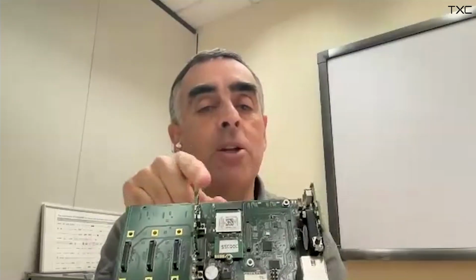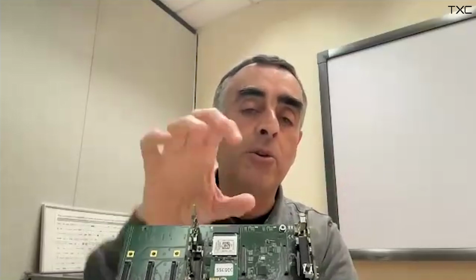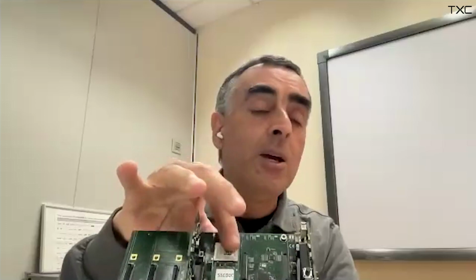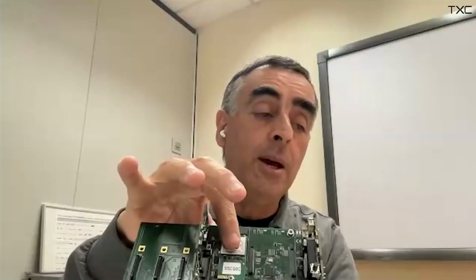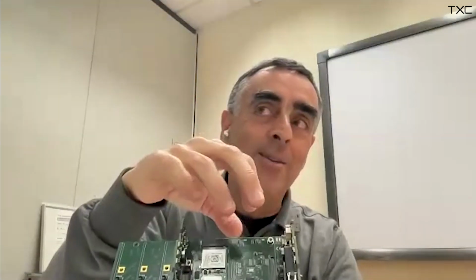So the way we do that is that we can individually manage the power to all these subsystems. So the microcontroller can shut off the compute module, remove power to the SSD unit, and turn back the Raspberry Pi on, so that the Raspberry Pi will be forced to boot from SD, for example.